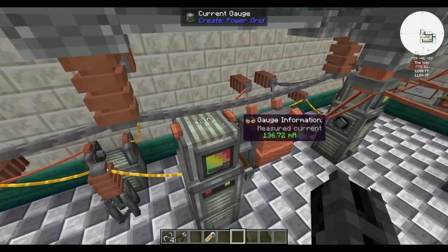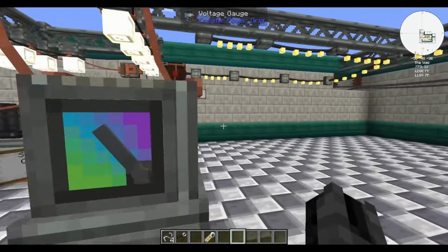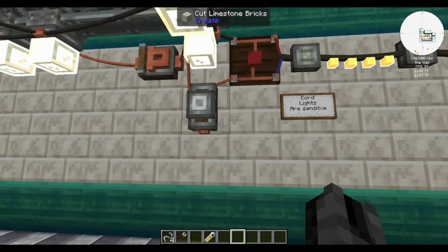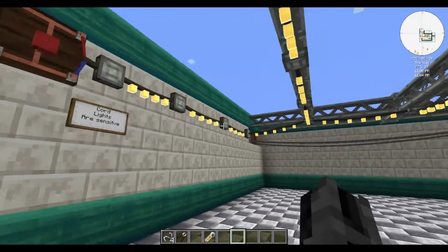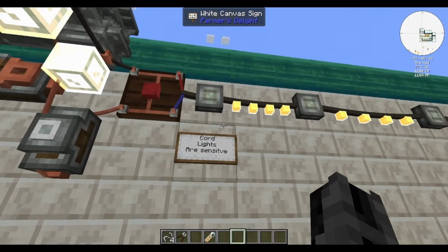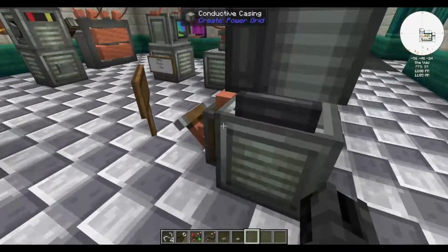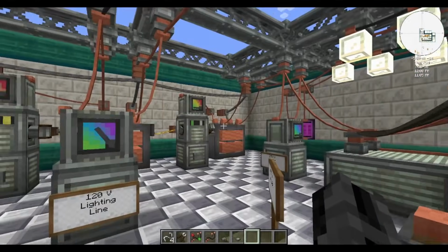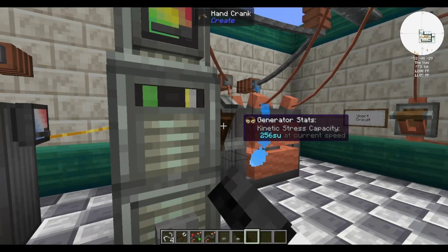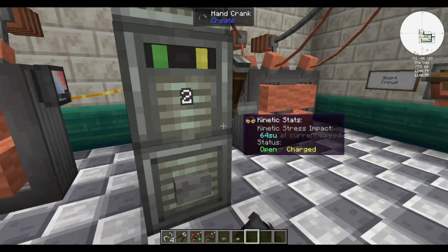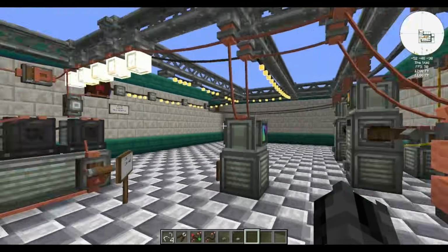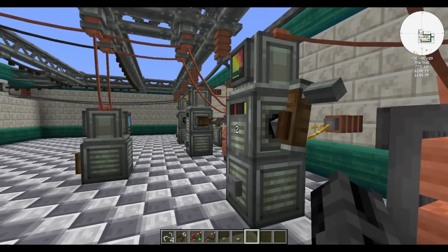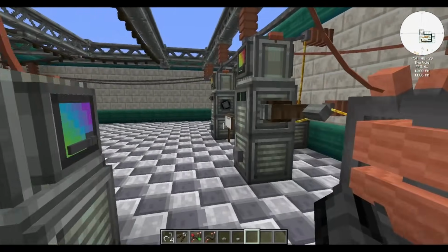And here are the gauges measuring the current coming through the breaker. And over here we can see that there are lights connected to it, everything's fine. In case we overload it, the breaker acts, disconnecting the circuit. Now let's say we make a short circuit on the main breaker, I think. This is just the light one. But the current was high enough to trip the main breaker.